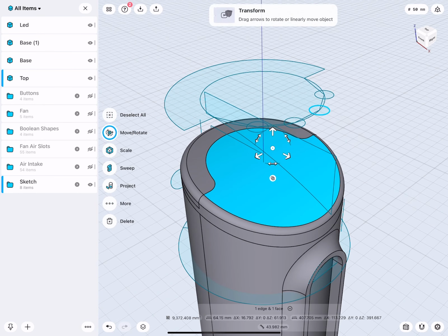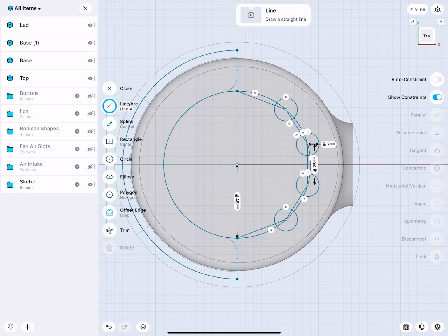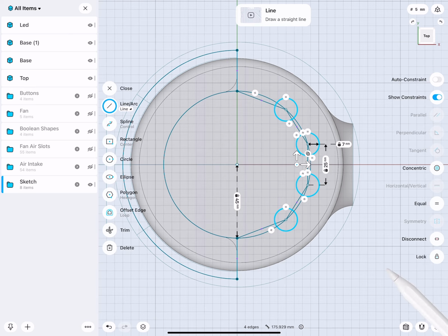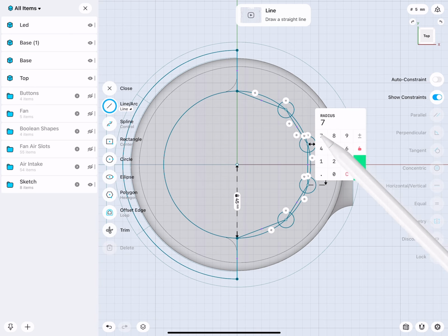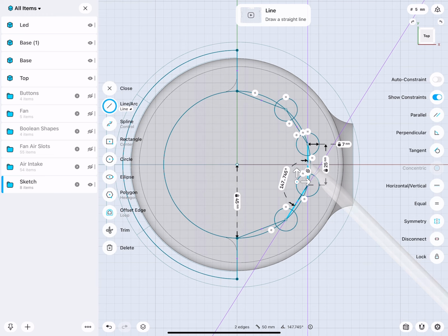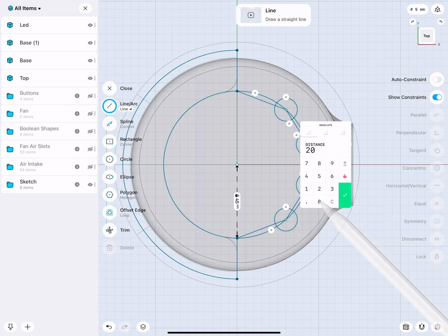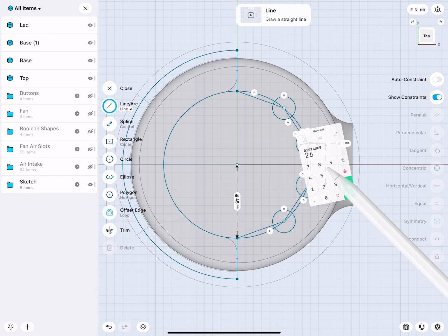Before we take a look at how to do this, let's examine actually the sketch. Also here, very simple trick how I set everything up to work nice and symmetrical. All the circles, for example, are equal. So when I adjust one circle, you see they all update. Plus I have from this point to the circle, from the circle to there and to there, I have all these lines drawn. You might ask yourself what these lines actually are. So I have 3 lines which are equal, and I have then 2 lines which are equal. Here, and check this out. When I set this to 20, there you can see how everything updates nicely.